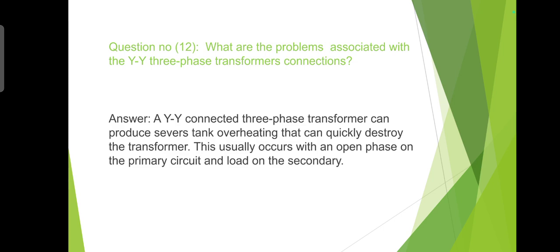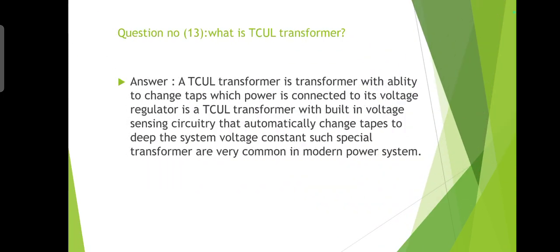Question number 12. What are the problems associated with the YY three-phase transformer connections? Answer: a YY connected three-phase transformer can produce severe overheating that can quickly deteriorate the transformer. This usually occurs with an open phase, the primary current and load on the secondary.